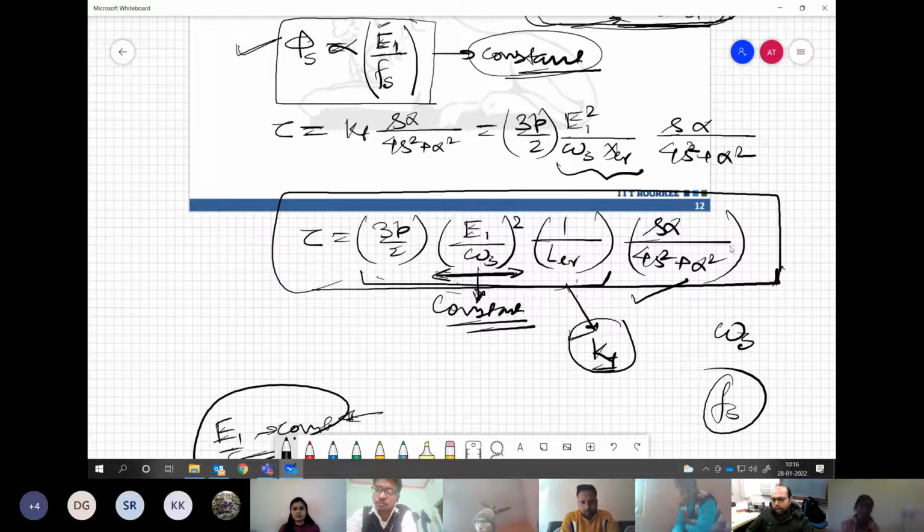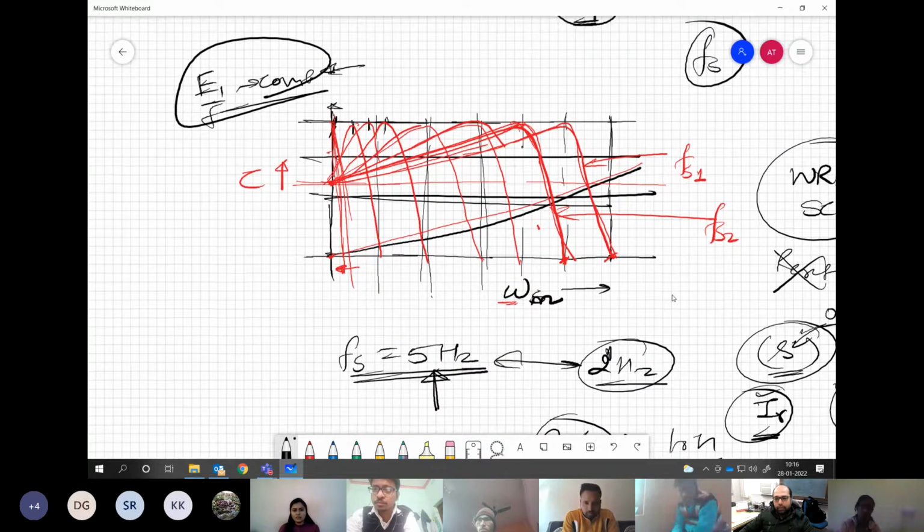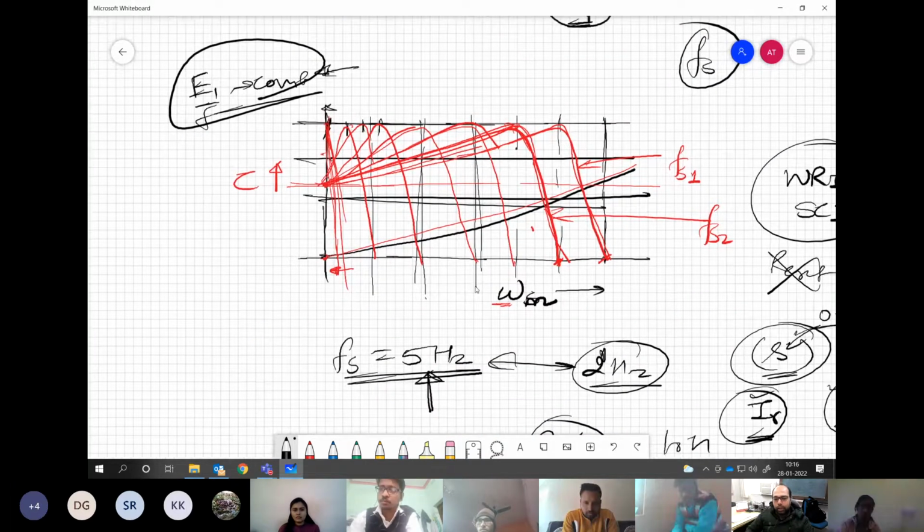So this is a very advantageous method, where we are not shifting or shrinking the torque speed characteristic and we are not unnecessarily burning power in some resistance somewhere, and still we are able to achieve good starting torque from the rotational speed point of view. So this is the torque speed characteristic corresponding to the rated value. And if you keep on changing the frequency while maintaining this E by F constant, you are shifting this characteristic while maintaining the shape as it is.